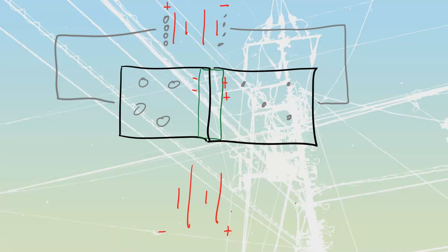Over here, I see on the battery that I've got a whole pile of electrons that are being pushed out of this battery by that chemical that's on the inside. Okay, we'll just draw a big slimy chemical on the inside there. They're being pushed out, which means that we're going to have more electrons that are going to travel down this, bigger marker here, and they're going to start to fill up inside of here. And as they fill up inside of here, they're going to be taking up more and more room. They're going to be pushing this barrier region smaller and smaller. And as they push it smaller and smaller, they're getting closer to this opposite side.